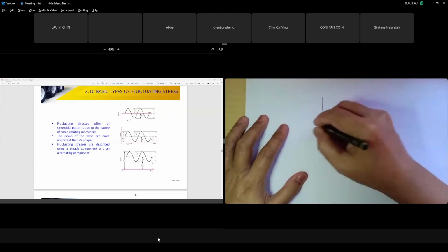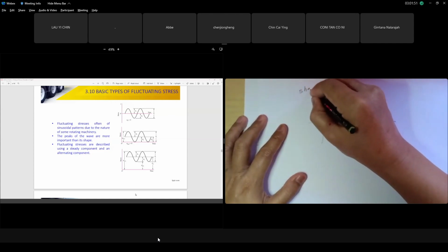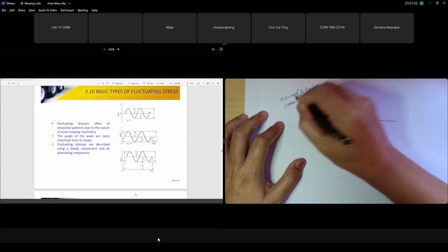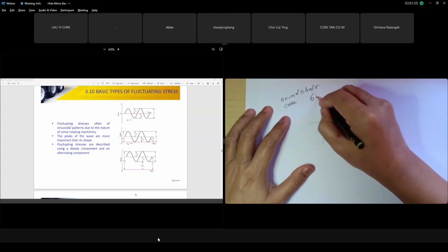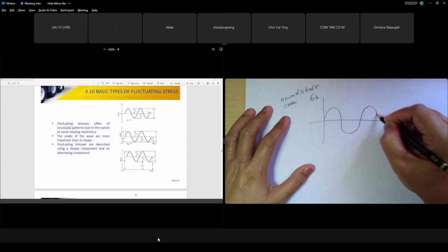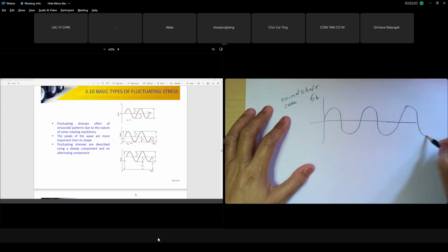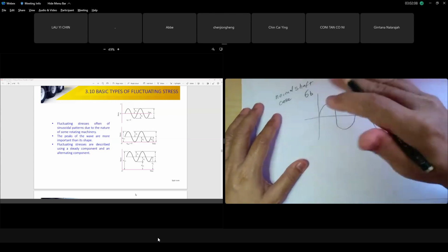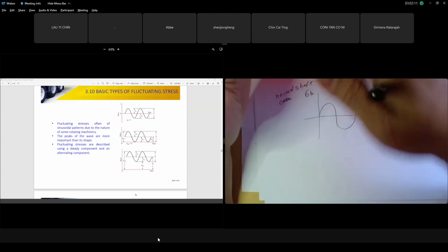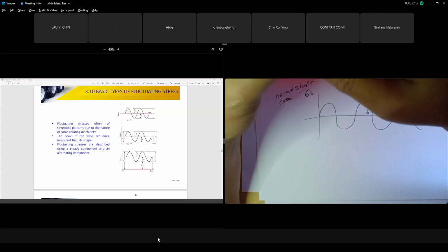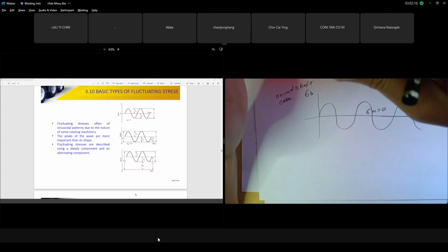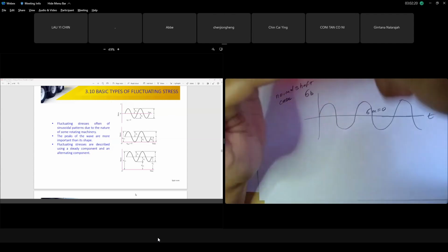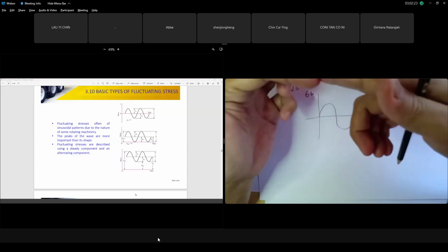So for a shaft, in the normal case, the bending is always completely reversed through time. This is your time axis. This is called completely reversed, because your element at section B, at the top, goes for tension, then rotates because the shaft rotates, so the element goes down. Bottom is compression, up is tension, bottom is compression, tension, compression. I'm talking about your bending stress.